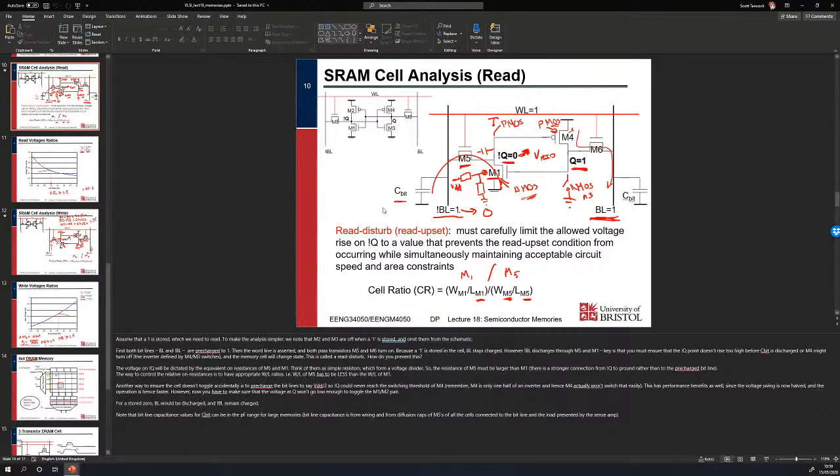Yes, so we are still looking at capacitances to a certain extent here. It's not quite sequential dynamic because there is a regenerative section in the center here. But yes, what we're doing is charging up parasitic intrinsic capacitances on either side of the cell and then using whichever inverter is outputting a 0 to discharge the appropriate bit line or inverted bit line, sapping all the charge out of the parasitic capacitance.